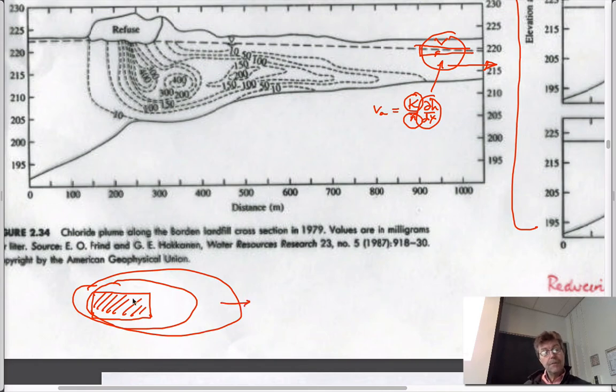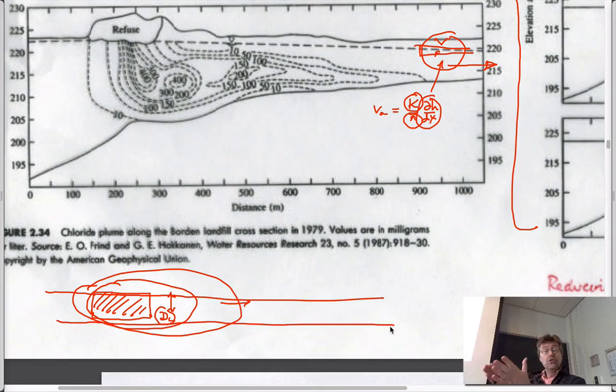And so if you represent this in some way, the magnitude of this lateral dispersion coefficient, D sub L, would control how widely it would spread. If you thought, for instance, the value of this was 0, then I suppose you might assume that really the distribution of the contaminant, you could think of it as just being held between two walls, can't disperse to the side transversely. I want to write that not as L, but transverse. I'm thinking lateral, so it's longitudinal we've used for L and T for transverse.